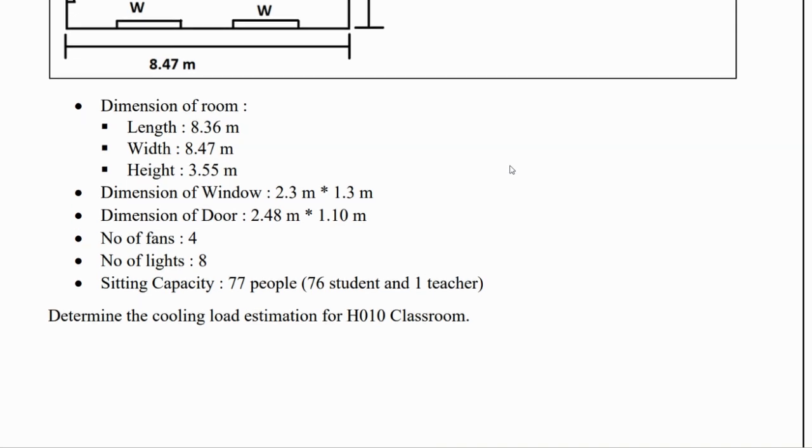Now what does a mechanical engineer do here? He will go and check the dimensions of the room initially, whether there is a sunroof or open roof, walls, windows and door, and all dimensions should be matched. And then he notes whether there are any other electronic devices such as speakers or sound systems, because they will dissipate heat, so that heat should also be removed from the room. And what is the capacity of that room, how many people sit there, all that data should be gathered and their total heat should be calculated before fitting the AC.